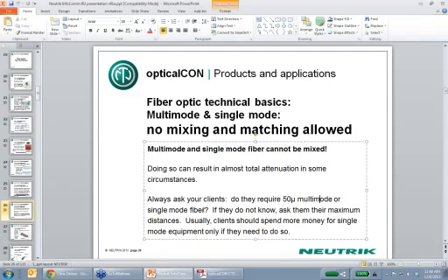Yes. We actually see a lot of it with, for example, these OB vans where people are trying to reduce costs and be able to put out a high-def outdoor broadcast van which doesn't cost too much money. We see it with some of this equipment. I want to say, by the way, that I think both Telecast and Telemetrics offer multimode options for their boxes, which will then connect up to other boxes. But the connection to the camera is typically single mode.